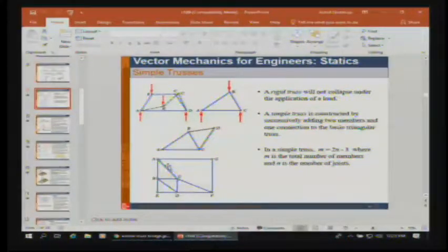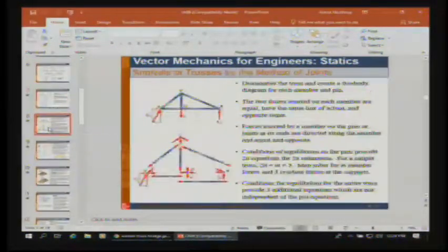Now, if you look at a truss like this, which is a square all the way around, and this kind of answers the question you were talking about earlier, we start building on triangles, and then at some point part of the feature may not be a triangle, but if it's still rigid, in other words, if pushing on G won't tend to splay A outward, which in this case it won't, it can still be a rigid truss. But the foundational piece of that truss is definitely the triangle. Okay. Yeah, you ask good questions. I appreciate that.